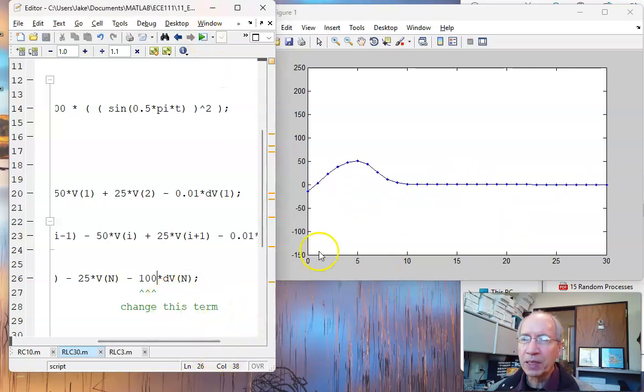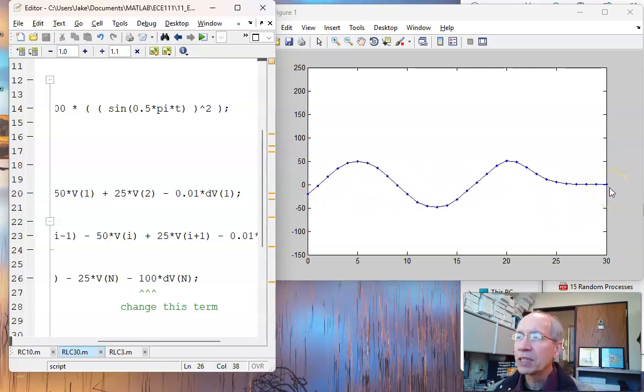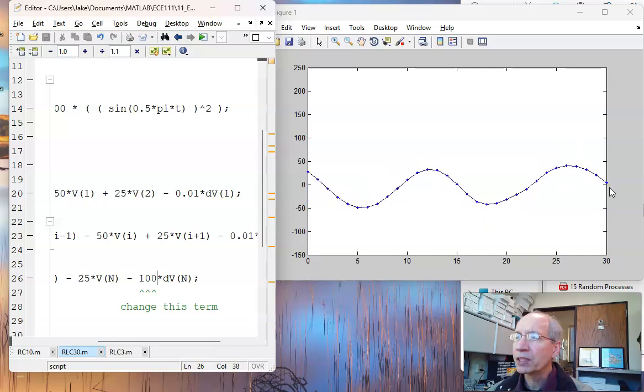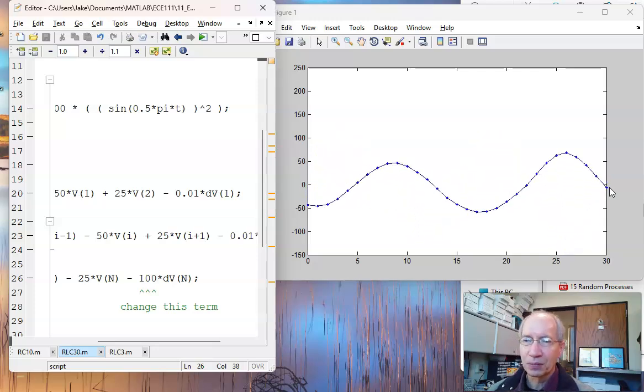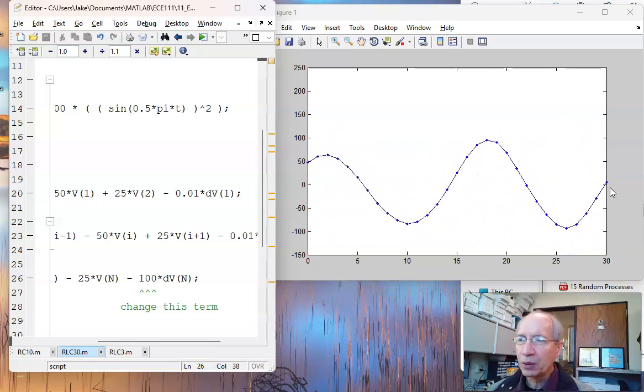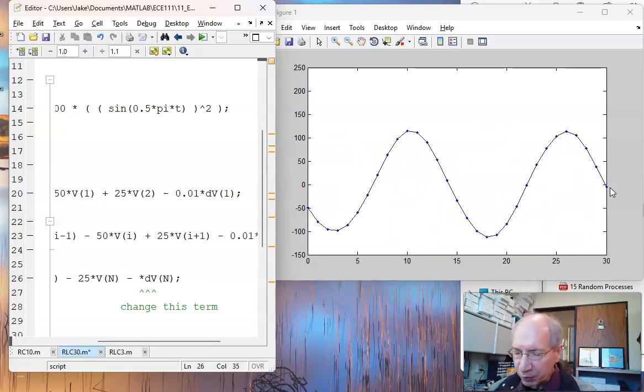So here, I made the right endpoint too stiff, so the right endpoint's just barely going to move. And once again, you'll see I get standing waves. So I hit the right endpoint, it barely moves, that causes a negative reflection. The reflections from the right plus the wave from the left give you standing waves. Again, that's kind of what you see in the Valparaiso Bridge. I get standing waves, that's going to cause the bridge to collapse. You see that on skyscrapers. To get rid of that, what I really need to do is get rid of reflections.